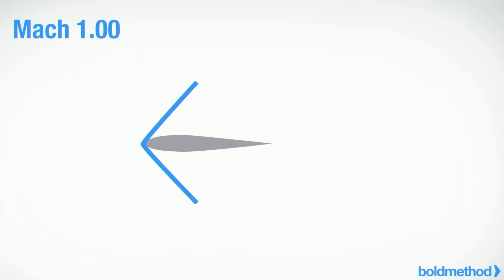And when we think about a shock wave on an airplane, that really is just airflow moving at the speed of sound. So if you go back and look at the iPad here, essentially at Mach 1, what you end up with is this big shock wave, because all the pressure that's being pushed forward by this airfoil can't travel any faster than the airfoil itself. So it just piles up and angles off. Okay.